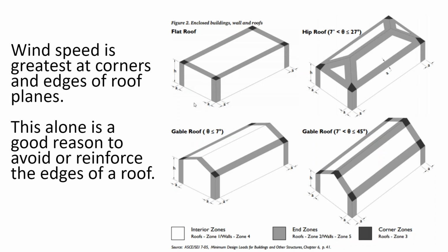possible on a residential rooftop, how do you stagger and distribute those attachments to best support the rooftop? And the answer is you want to support the corners and the edges more than you would the interior of the array. And on top of that, staying to the interior of the roof surface will subject the roof and the array to less wind load than the corners.